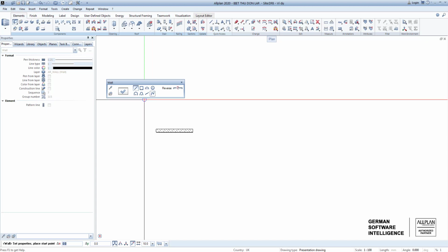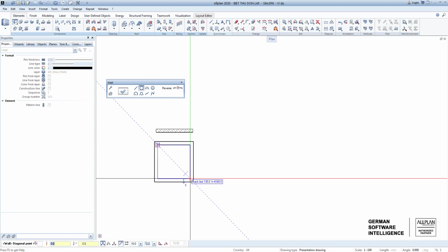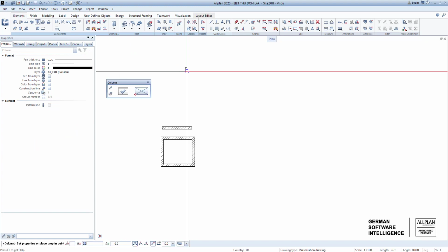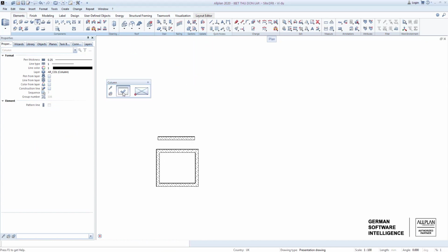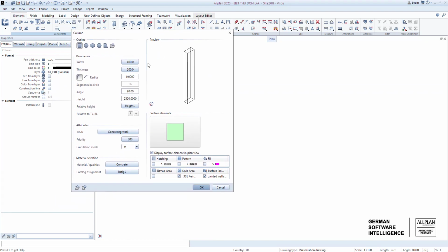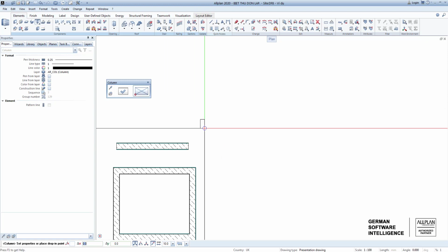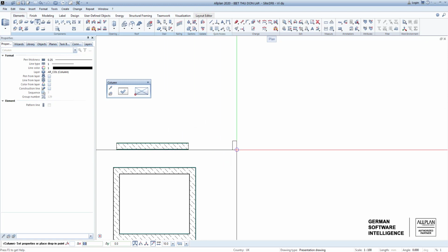Besides, Allplan also provides some types of generating wall, such as rectangular component. We also do this way for columns. Select the column icon, then press this to set the properties. Change geometry, parameters, stroke, end formats, or display properties. You enter accordingly and select OK. Choose the column position with different anchor points.